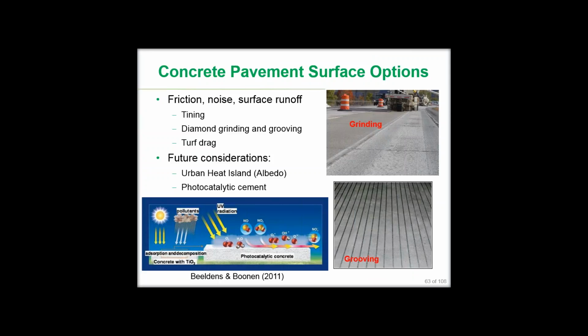Now, relative to asphalt, we don't generally put thin surfaces on concrete pavements as they do on asphalt pavements, or different surface courses, but we do have other means to provide higher friction through tining, through grinding and grooving, or different types of turf drag approaches. This can affect the friction, the noise, and the ability to have rapid surface runoff of the water. So these are current surface options that exist on concrete pavements.